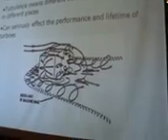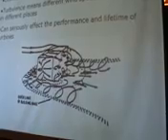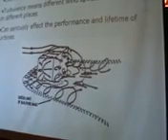In working out where you could put a turbine, where might be a good place to put it, there's a thing called turbulence. That means messy wind, really. It means wind going in different directions, different strengths in different places, just all over the place. And that's very difficult to extract energy from efficiently for a turbine. It can even shorten the lifetime of a turbine, and it reduces the speed and the output. So you want to avoid places where the wind isn't flowing smoothly.